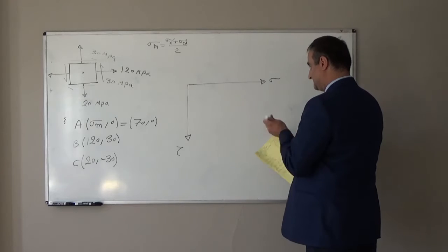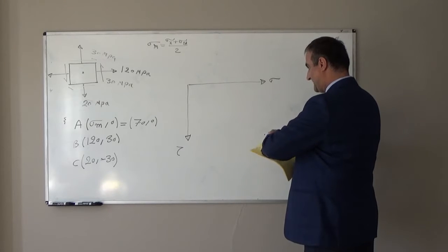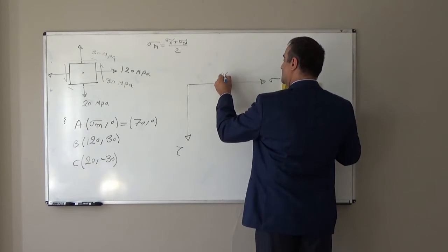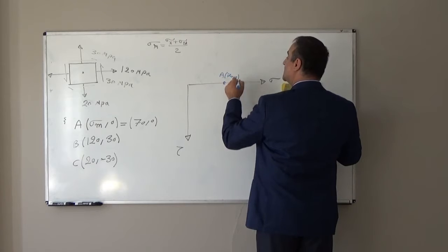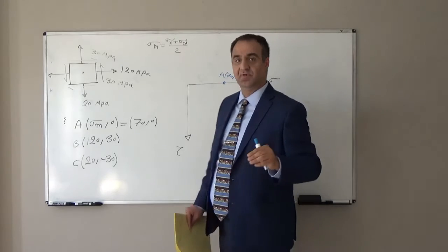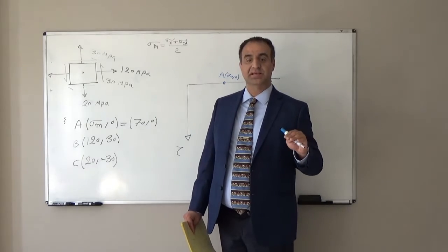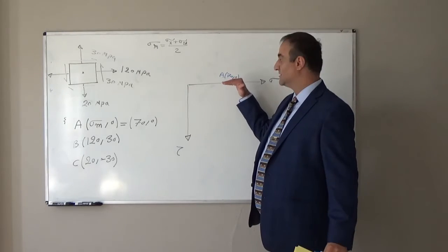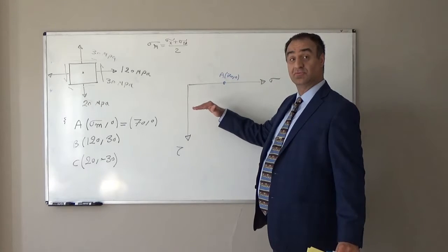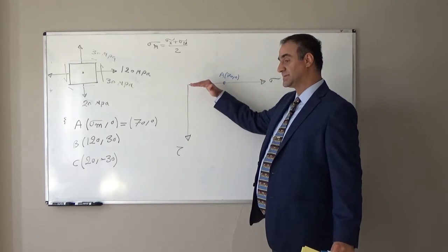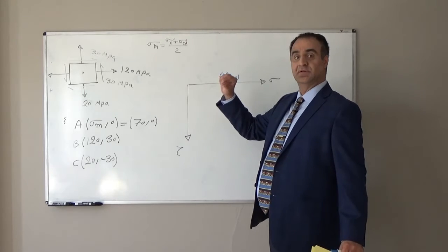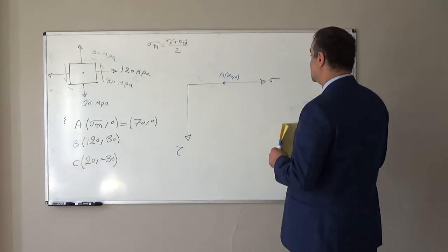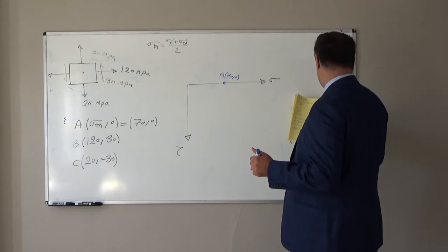The center point will be 70 and 0. For example, here, point A is 70 and 0. Pay attention, the center of Mohr's circle always lies on the sigma axis, so tau for that should be equal to 0. So A will be 70 and 0.